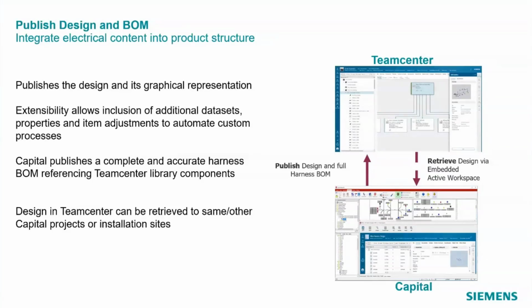So in addition to the design content, a full bill of materials from a Harness XC or harness designs can also be published into the Teamcenter BOM structure under the item. And this is where the link to the component in Teamcenter becomes extremely important, as the BOM line in Teamcenter has to reference a Teamcenter item. So we have to establish that link to the component so that when we publish the BOM, it all hangs